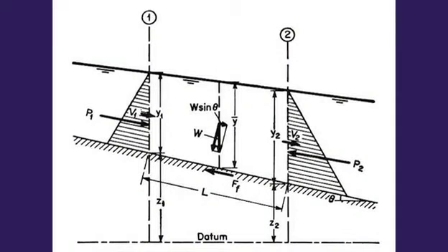And 4. Inertial. The gravitational force arises due to the non-zero bottom slope of typical open channels. The frictional force arises due to the non-zero boundary friction in open channels in nature. The pressure gradient force arises due to the depth difference between upstream and downstream cross-sections under gradually varied flow. The inertia force arises due to the dynamics of the flow. The imbalance between the other three forces produces a balancing inertia force.